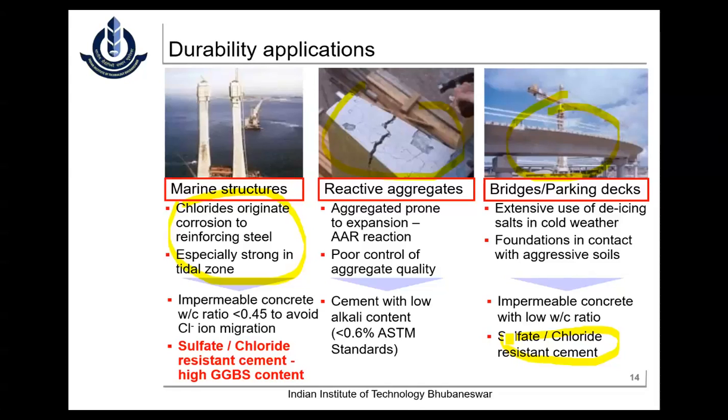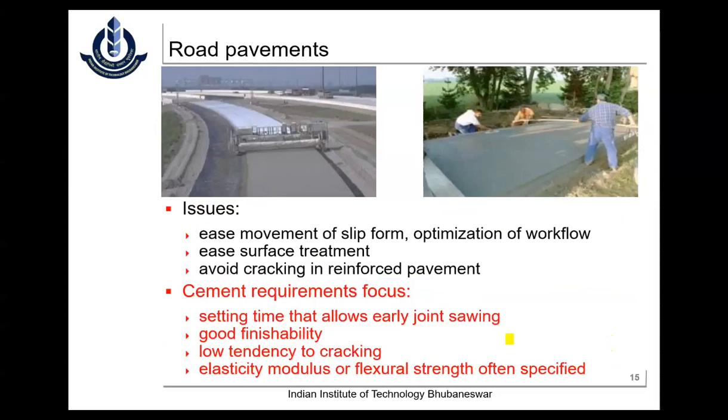There is one question which has been put up. That is, what is the purpose of mentioning a minimum limit of blending percentage in PPC? Like we have 15 to 35%. What is the purpose of mentioning a minimum limit? You know, that is from the durability perspective. We need to ensure that some percentage of fly ash is there. Any inputs from your side, sir?